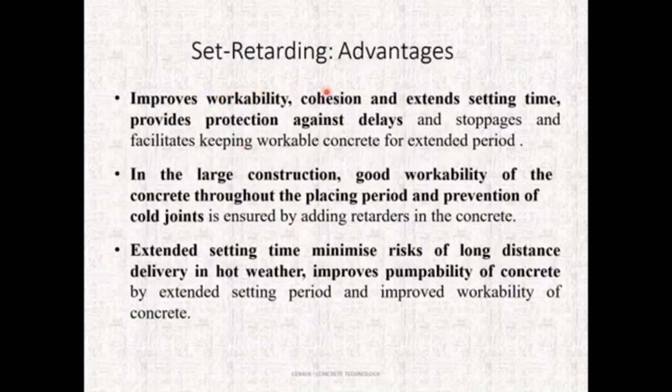What are the advantages of using retarders? It improves workability, cohesion, and extends the setting time. Hence, it provides protection against delays and stoppages, and facilitates the workability of the concrete for an extended period.